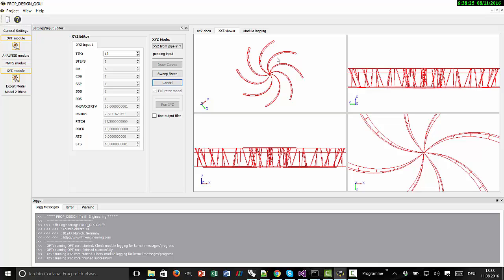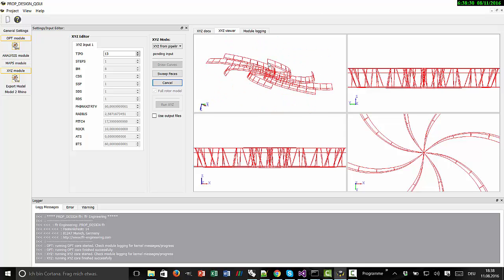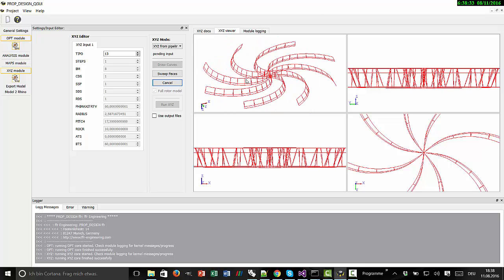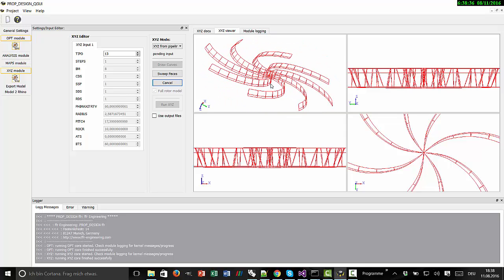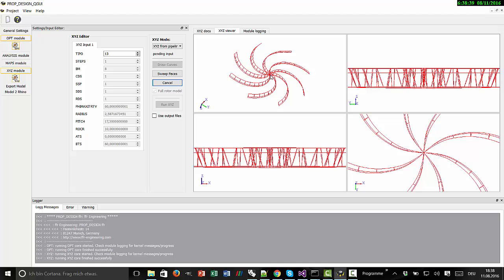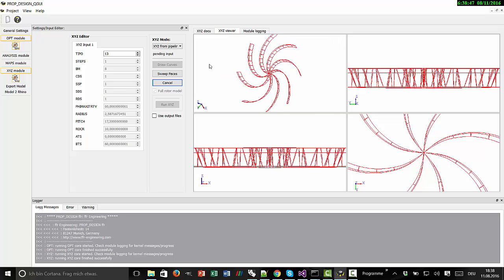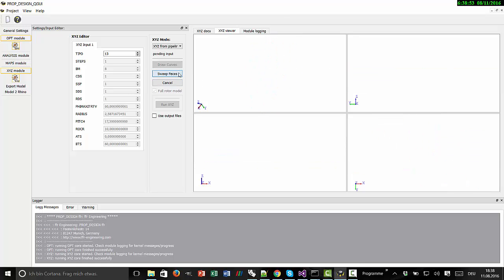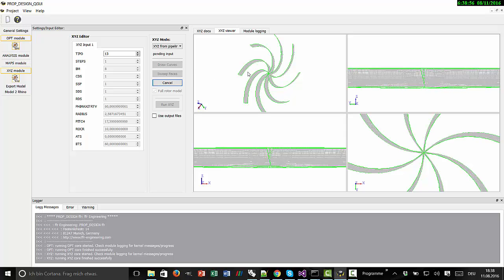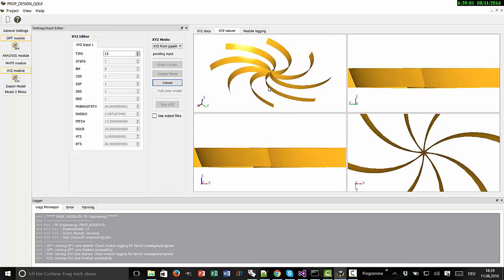You end up with something like this, and I also want to draw your attention to the fact that we now draw here in between all the different cross sections. So basically this is the discrete model of the wing on which you are computing the analysis, and now you could imagine that starting from there you have this helix-like wake for the other dimension where you sample the velocity field. And now you can also sweep the faces for this model, and if we again change to shaded, you see here that you have a CAD model which you can also export.